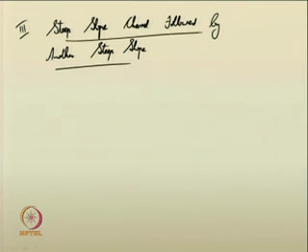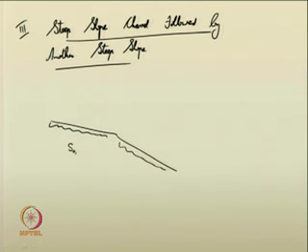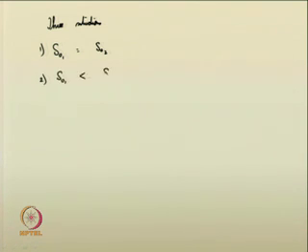What happens if a steep slope channel is followed by another steep slope channel? You can again think of the thing, a steep slope channel followed by another steep slope channel. So, this is having bed slopes S01, S02, both are steep slope channels. How can the flow profiles be? So, three situations you can imagine, that is S01 is equal to S02, S01 less than S02.